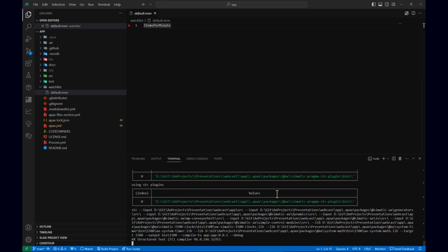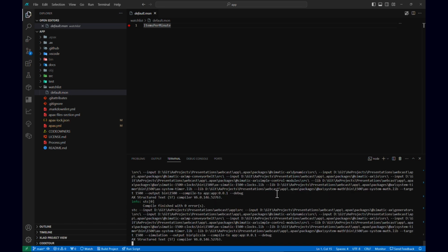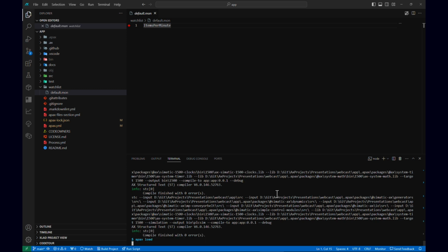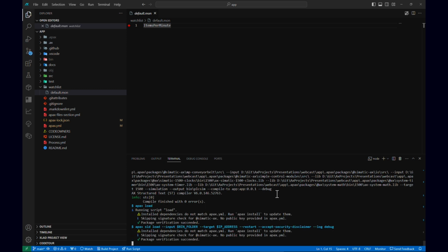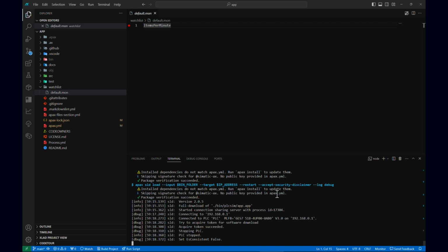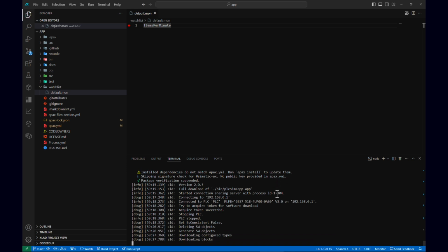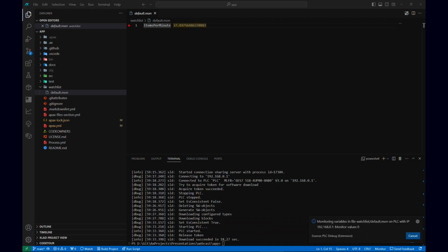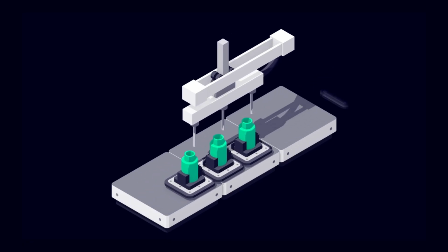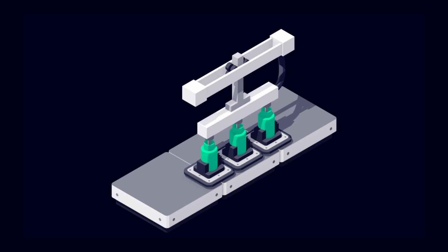A download to the PLC via a script is started. And within it, the code will be compiled and then loaded to our PLC via our SIMATIC AX loader. Once it is finished, the code is deployed. In the monitoring, we can see the values changed, so we identified that the process is running differently. And if we look at our operating machine, it is running smoothly.